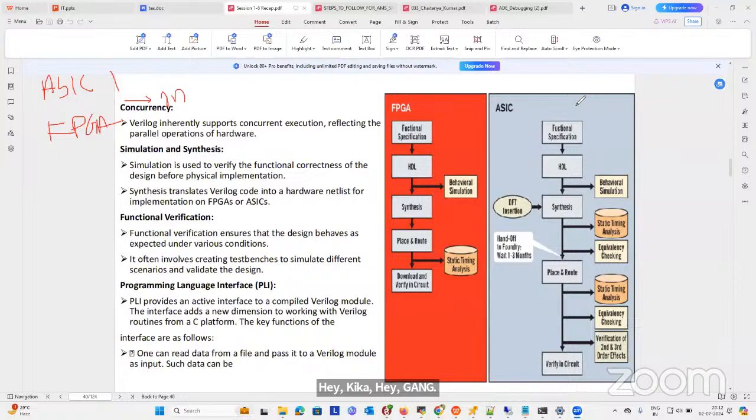So we need to design the devices by doping, by creating the terminals for a MOSFET, which metal we have to use for gate, which metal we have to use for source, drain, poly, oxide. All these properties we are going to define in a code format in TCAD or Silvaco. This is all about device modeling. This is also called applied physics sometimes.